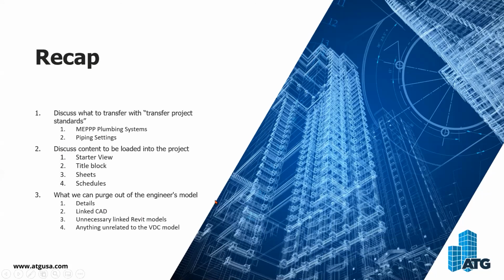Also, we'll clear out any of the linked CAD stuff that we may not need. Keep in mind, you guys may need to deal with some site stuff, and we know a lot of site stuff still comes across as linked CAD. We can keep those files in there, but the rest of the stuff, maybe linked CAD from a detail that they just didn't have in Revit yet or converted over, you can clear through all that stuff, knock that out. That will definitely help on performance.